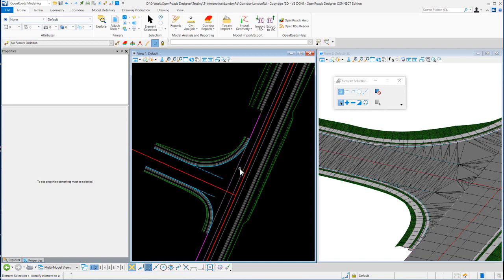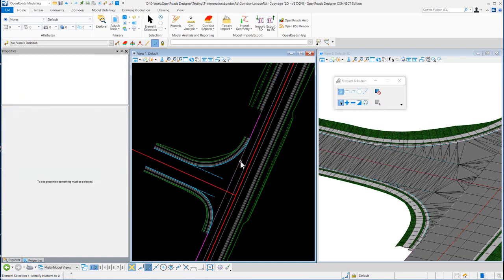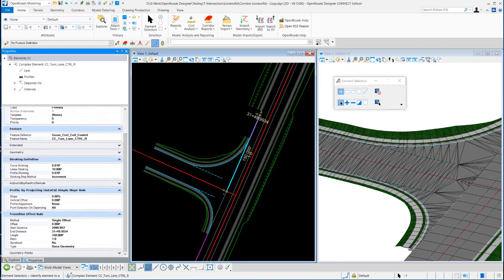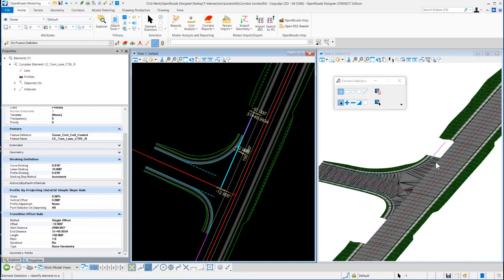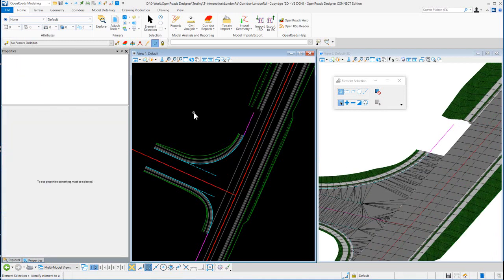Alright, so my last little horizontal edit, I'm going to come back in and choose this, right click until I get to that turn lane control. And I'm going to change that offset from 0 to -12. Basically what I did, I made room for a turn lane. And then what we'll do next is actually go place a turn lane civil cell.